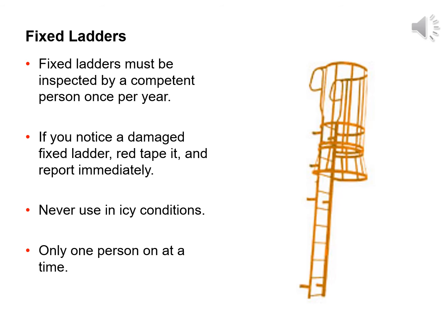If you are climbing a fixed ladder and notice that a rung, foot, gate, or any other part of the ladder is damaged, red tape the ladder, and report it immediately. Steps, rungs, gripping surfaces and platforms must be kept free of oil, grease or slippery materials. When ice or frost conditions are present, fixed ladders should not be used.